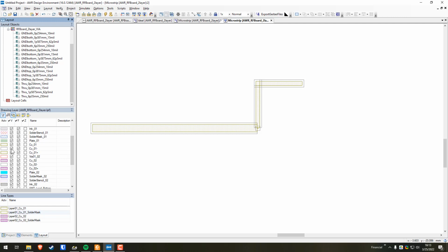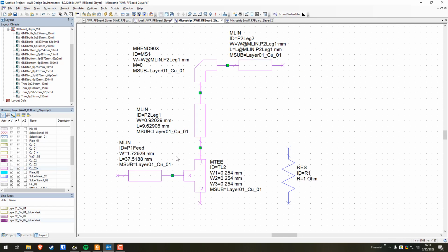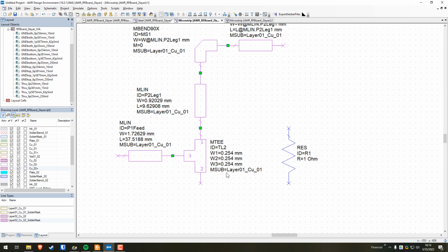And what you can do is deselect the visibility for copper 1 negative and copper 1 positive. And then we're also going to deselect it for copper 2 negative and copper 2 positive. Don't worry about that. It has to do with some kind of safety margin thing that is built into the software. So don't fret about that too much.